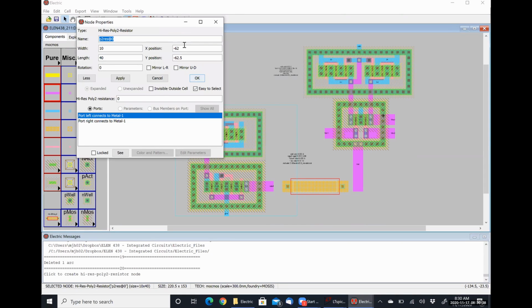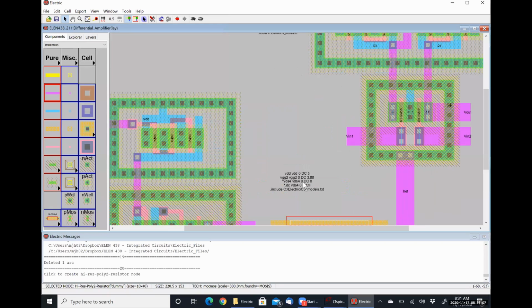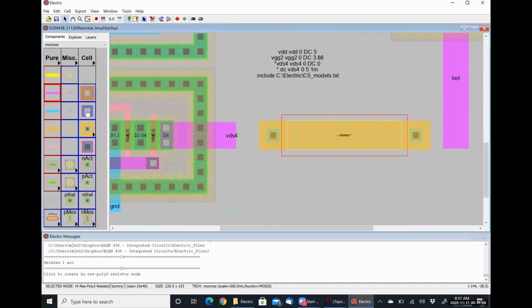So I'm just going to name this guy dummy because it's a dummy resistor, and it's going to have a very, very small resistance, so that any current that we see flowing through this resistor should be representative of the current that's being output by our current mirror. This is just me kind of troubleshooting what's going on. I'm going to have to connect metal 2.